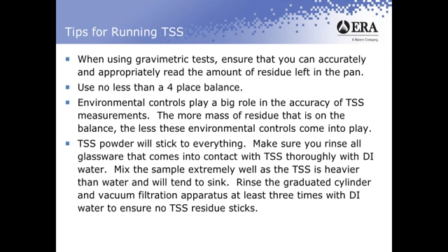You want to remember that TSS is heavier than the water that's in there, so eventually it will sink down to the bottom. After you mix your sample real well, you're going to pour a certain amount of that sample into a graduated cylinder to give you your volume, and then you'll pour the sample from your graduated cylinder into your vacuum filtration apparatus. Now, a portion of what's in that graduated cylinder is going to stick. So you want to rinse that graduated cylinder a minimum of 3 times with DI water and pour those rinsings through your vacuum apparatus.